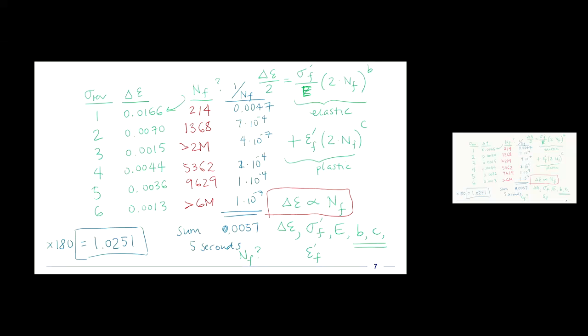Right? So this is our cumulative damage number. And Palmgren-Miner says if we go above 1, then we would expect failure. So we're really close, but not exact. And we've identified which magnitudes of both stress and strain correspond with the majority of this damage accumulation, which is the one with the biggest strain change, that first one we identified up here. Okay, so does that make a lot of sense to everyone? Yeah? Okay, so not too difficult.